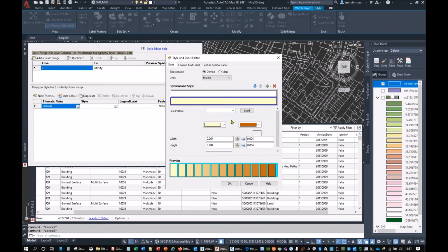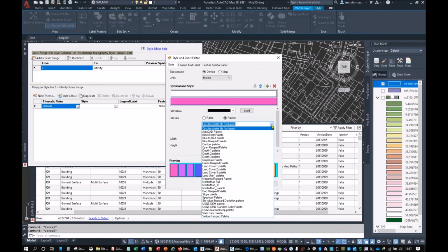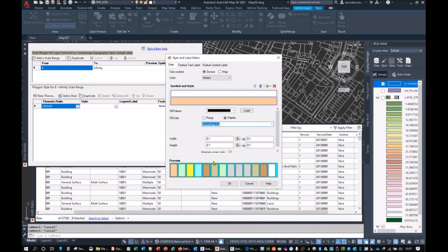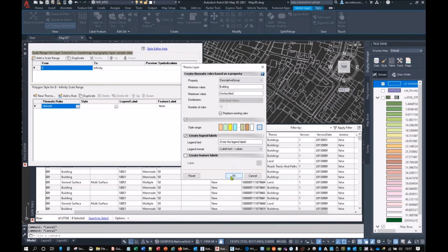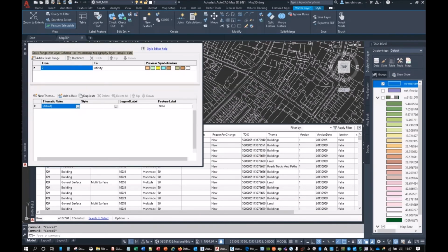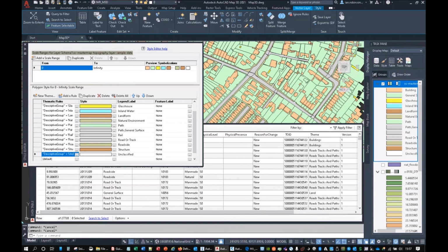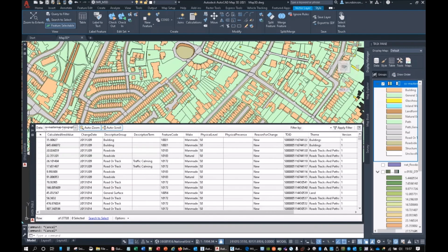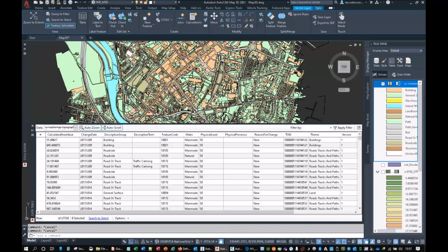And then for here, you can go in and you can use style palettes. You may have to make some. It doesn't come in the box, this master map one. I can send you this if you need it, but it's a bit awkward, I have to be honest. They're not perfect, because if you have master map that doesn't have greenhouses in, then it'll skip one and you'll end up with yellow roads instead, that sort of thing. There we are. We can colour it up.